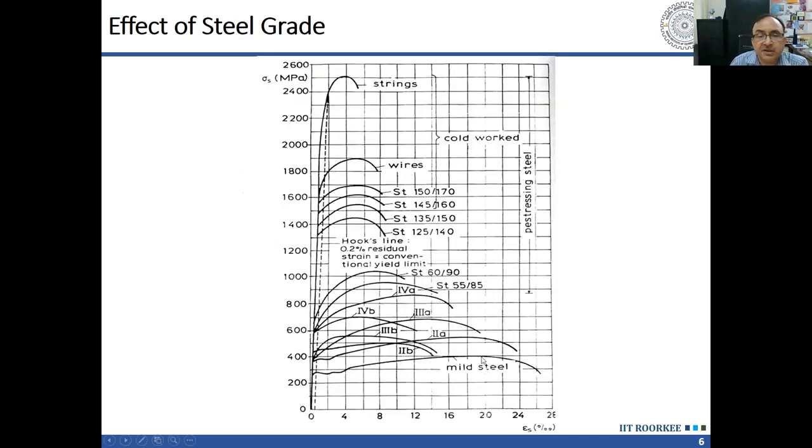On the other hand, in steel, the minimum elongation was 14.5%, and the yield strain is something like 0.125. So here we are getting a ductility ratio of more than 100. That much ductility is available from steel, more than 100, and there we are having 2. So we can understand how much more ductile steel is as compared to concrete.